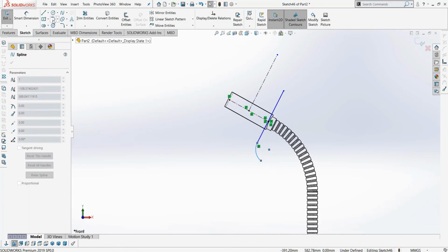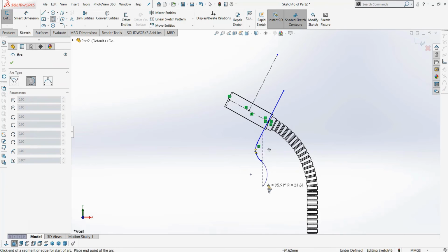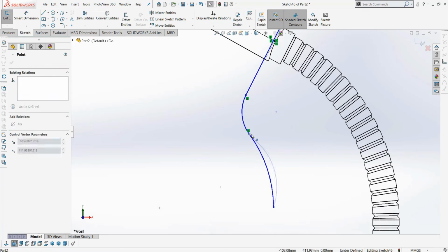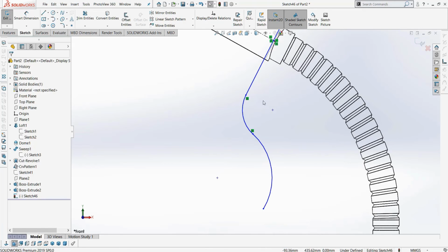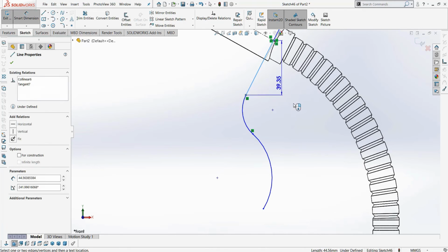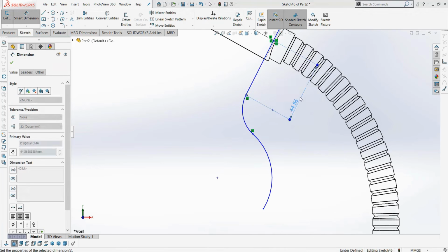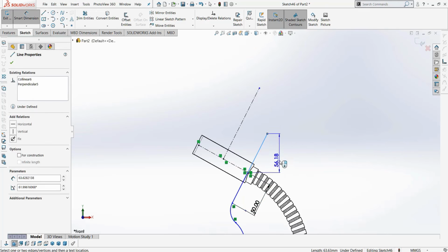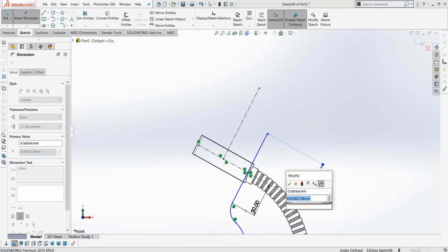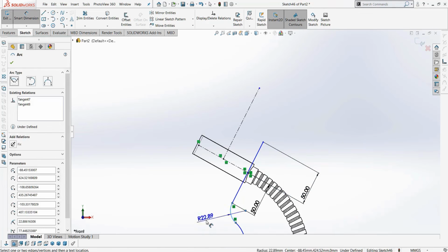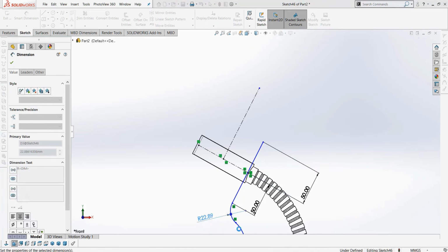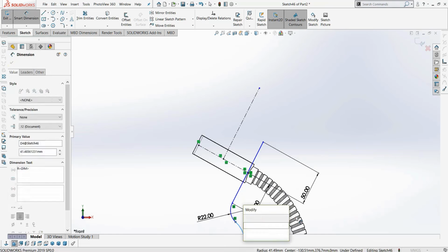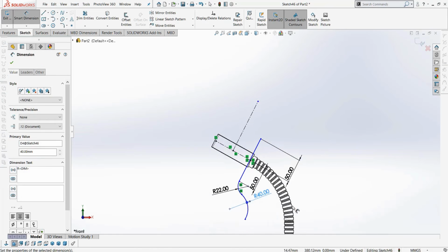Of course, the fact that the spline goes back is something you will see: it always tries to maintain a tangent state in front, or the same tangent condition of our work. If you use this arc, it has another advantage: you can give it a smart dimension, unlike the pillars that are now not selectable. But right now, here is a half arch that we will address. This is 22, and this is 40.